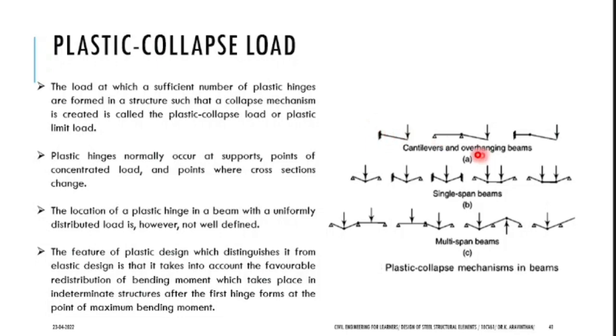Okay. Now what is this type of beam here? This is an overhanging beam. You have two supports. What are they? Both are hinged supports. So this is one hinge and another hinge. You have two hinged supports, and when you keep increasing the load, the plastic hinge will occur at this point, the hinged point here.